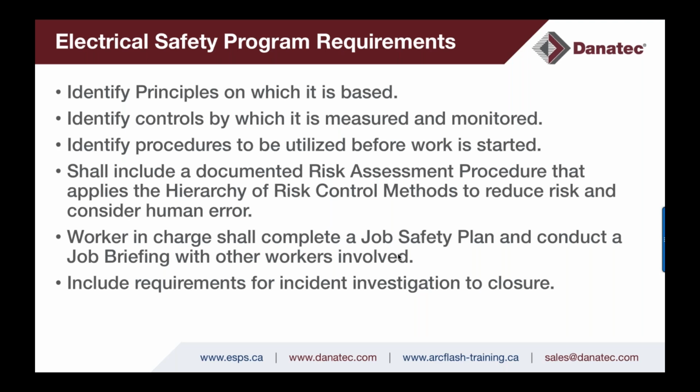So we apply the hierarchy of risk control methods in implementing the overall energized electrical work task risk assessment procedure, again, to drive down the initial risk level so that our residual risk level is acceptable or as low as reasonably practicable. There's risk language that was in the 2015 standards that is now still in the 2018, and there's more of a requirement for you to understand this risk language and be able to apply, again, this overall risk assessment procedure.